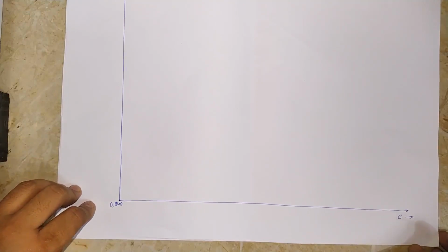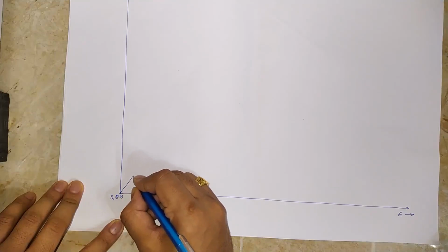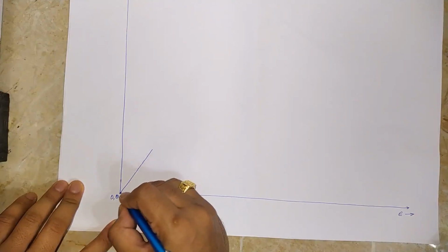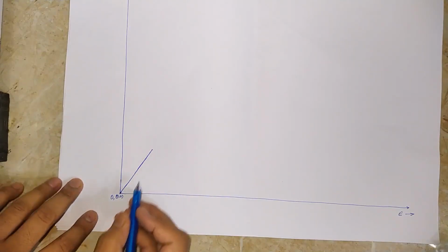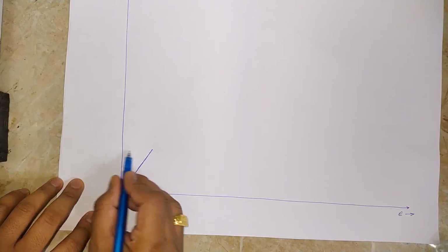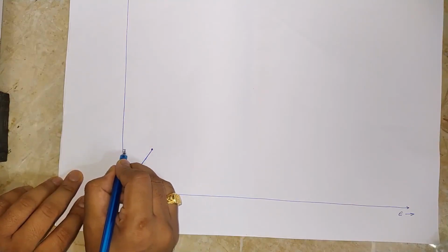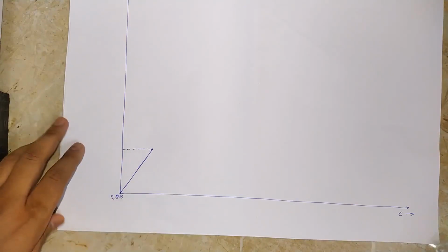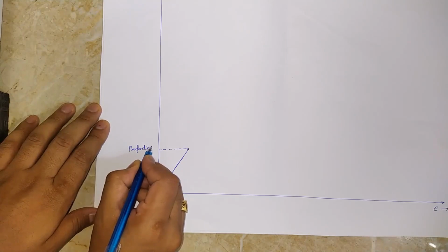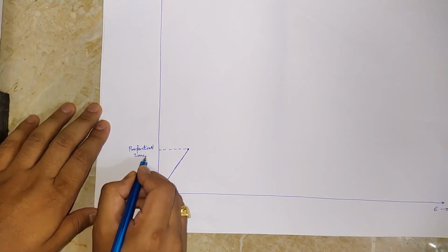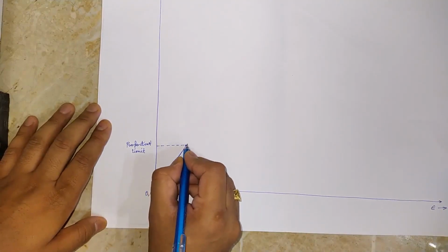Okay, so as we elongate the material, as we elongate the specimen, we get this kind of a curve. As we keep on increasing the elongation, we find that the resistance offered by the material also increases proportionally, and this proportional relationship holds up to point A, which is called the proportional limit. So the stress corresponding to point A is called the proportional limit. Let us see, it's point A.